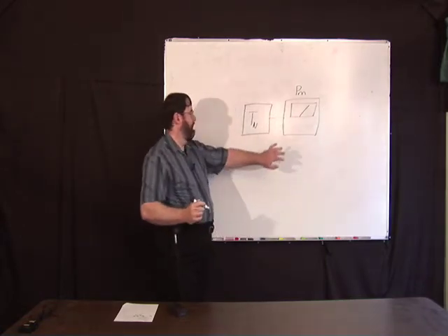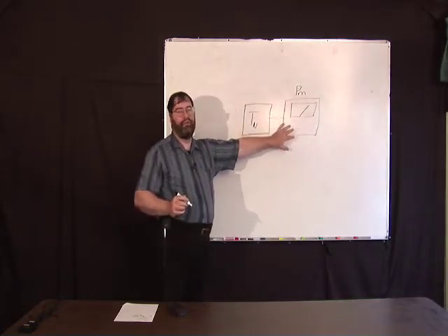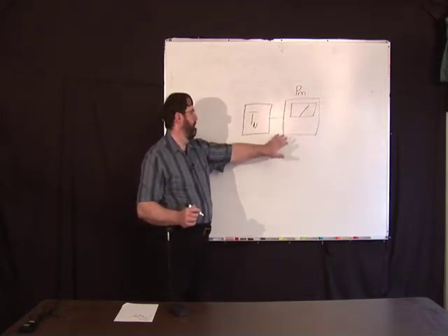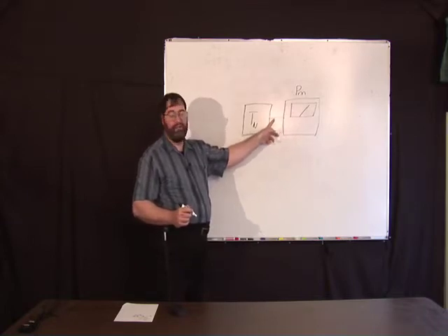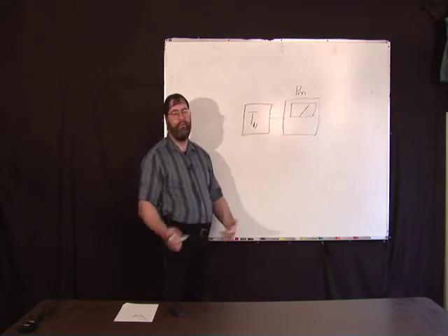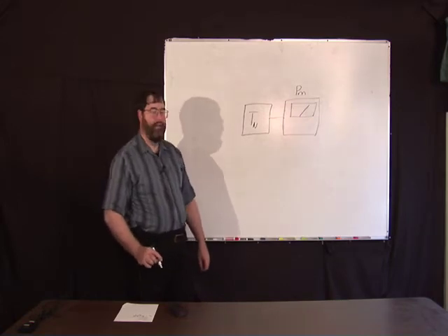Unfortunately, with this setup, there's going to be some noise generated by the measurement system itself. You're going to have losses due to the transmission lines, mismatches, and you also have the problem that since the transmission lines are at finite temperature, they also contribute to the noise as well as take away from the noise power.